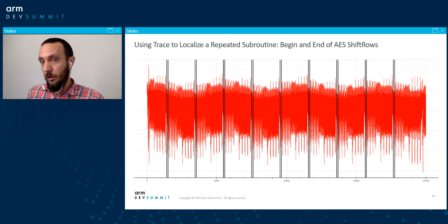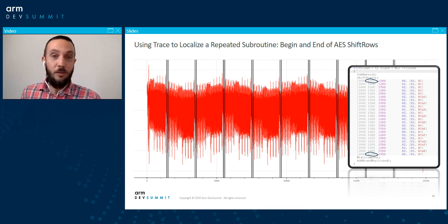You can go a little bit further. With the PC address matching, you're able to specify 2 different addresses on which you will get PC matches. You can change these over time, of course, but for a given execution run, you're limited to 2 addresses. So you can say, okay, how about instead of just plotting a specific address, let's look